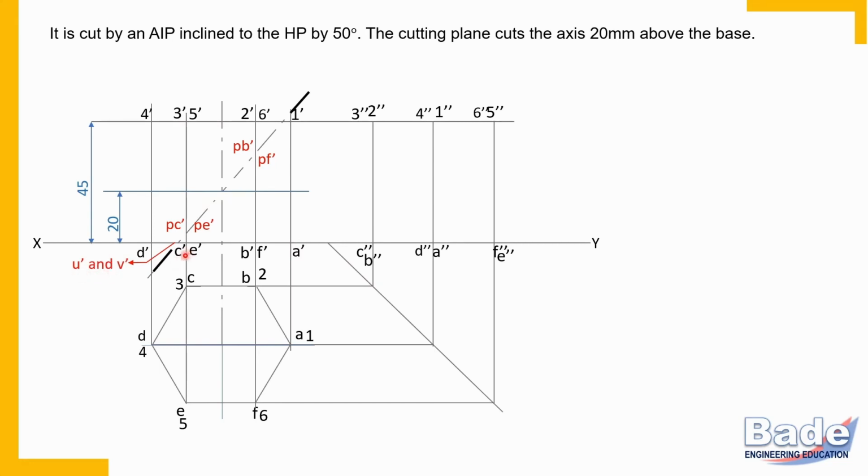Now, it's not a pyramid, it's a prism. It has a surface at the top, identical to the base. So where the cutting plane line intersects the top surface, here also it intersects 2 edges at the top. So label these points with letters S and T.